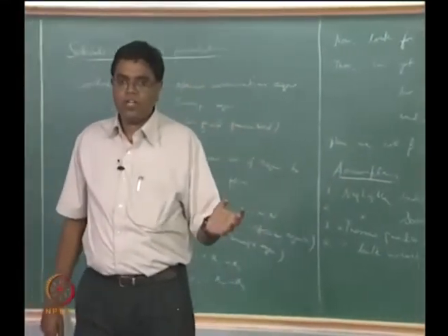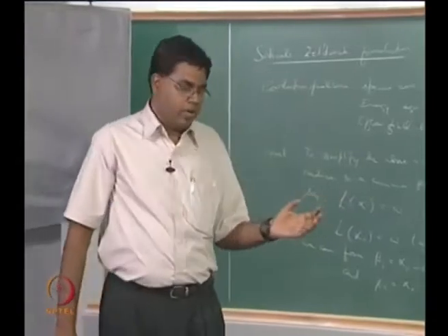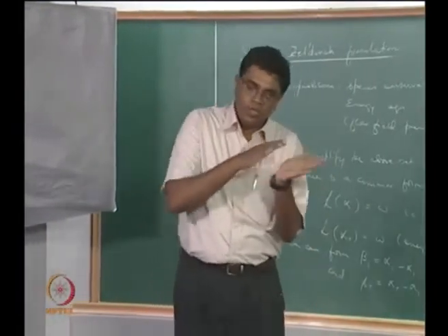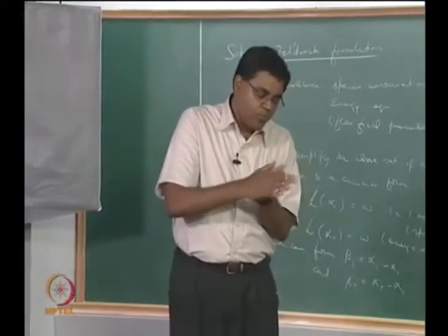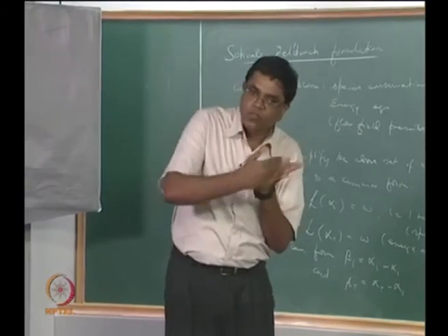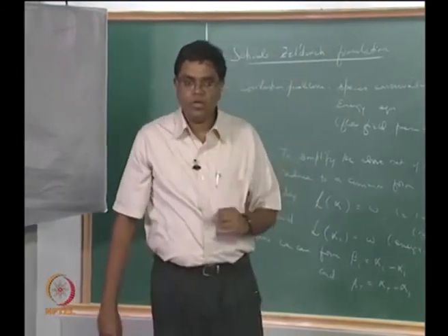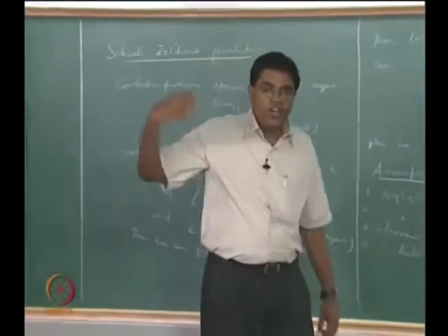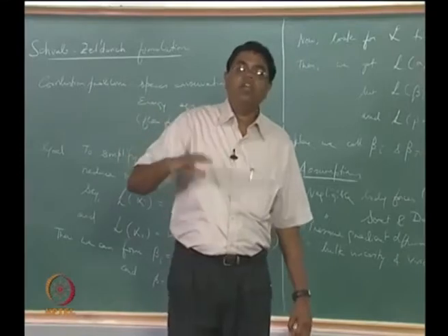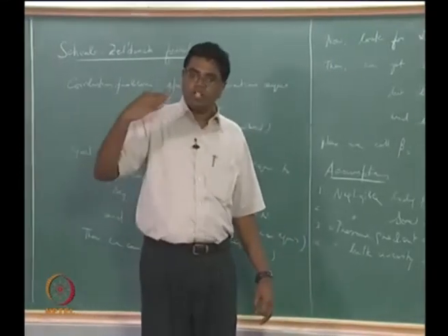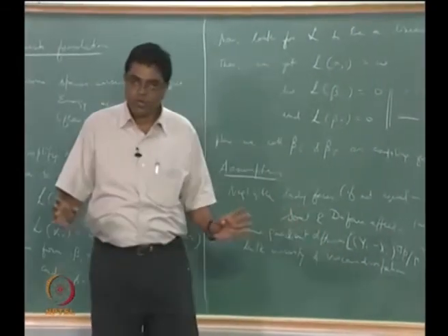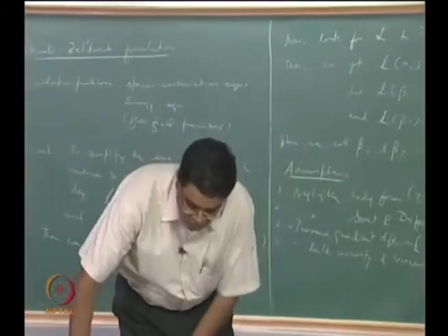If you now do an order of magnitude analysis, unless you are looking at situations of tribology, like when you have two surfaces that are in very close clearances and you had a fluid in between, like in lubrication and so on, or if you had re-entry effects where your Mach numbers are so large and the boundary layer is so thin with a steep gradient, effectively you are looking for very large gradients of velocity. That is when viscous dissipation is significant, otherwise you do not have to worry about it, not typically in our application.